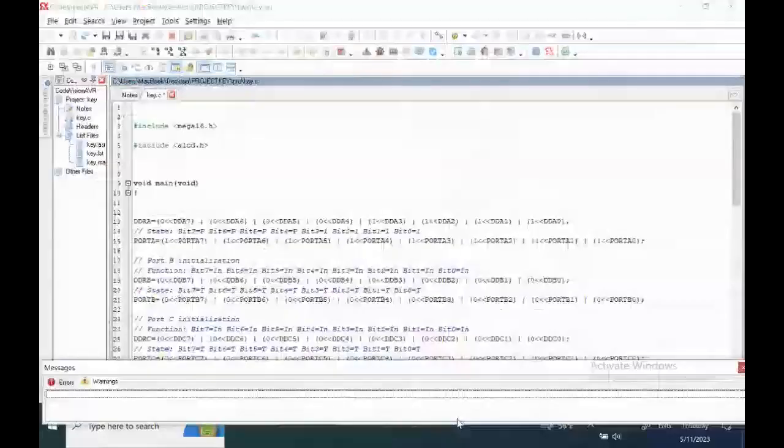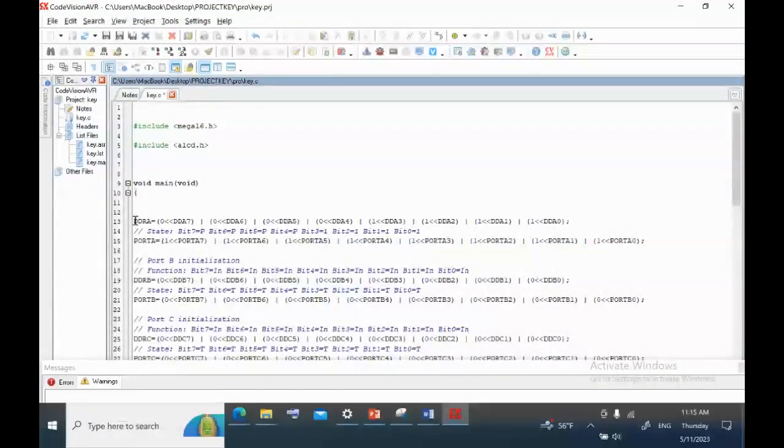If we want to erase this code, then we should write the code related to configuring the bits as input and output. You know that we made some changes in Code Wizard, and we configured the pins of this port as input and output. If we erase this one, we should write the code related to configuring port A first bits as output and last bits as input. To do that, we should write which code?